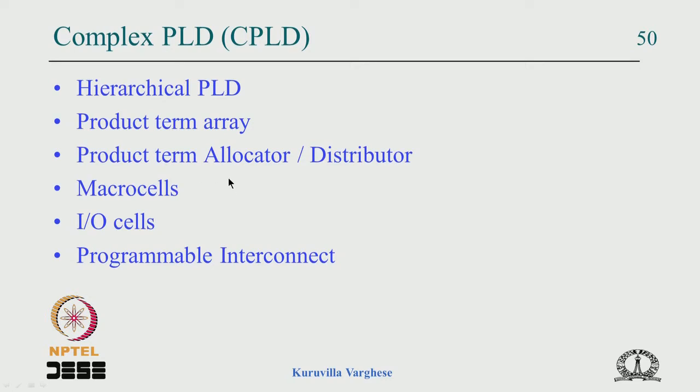It depends on the design, maybe that in the design there is an FSM which needs to reset a counter under some condition. Then a global reset wouldn't help. A global reset helps during the power on.